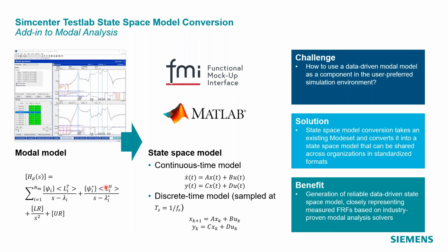What is the idea here? The idea is to take a modal model, as I was explaining before. So we have mode shapes, natural frequencies, damping ratios. And we want to put that in a model that also can be used in other environments. And then the state space model is very well suited. It's a kind of an input-output model.